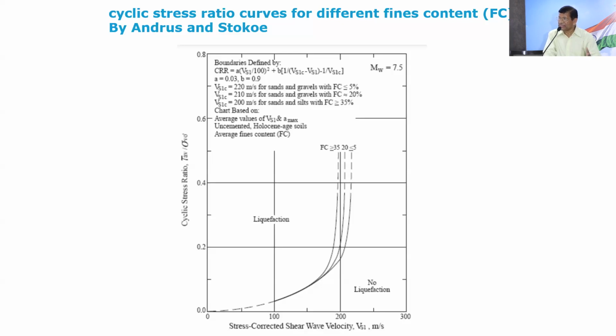If our velocity is less than that, the soil can liquefy, meaning during cyclic liquefaction. And if it is higher than that, we are good, it will not liquefy. So this is again another guideline you can follow. But again, we do the numerical model and see whether it is liquefying or not.